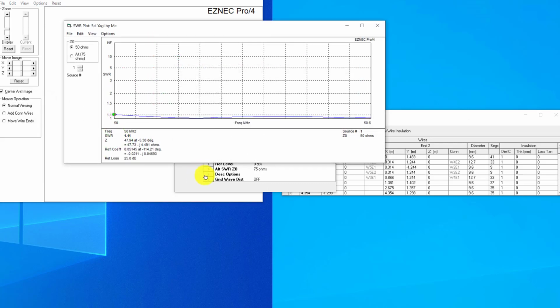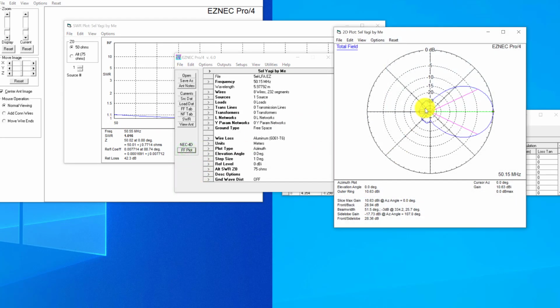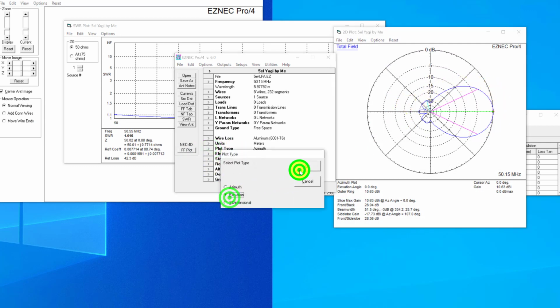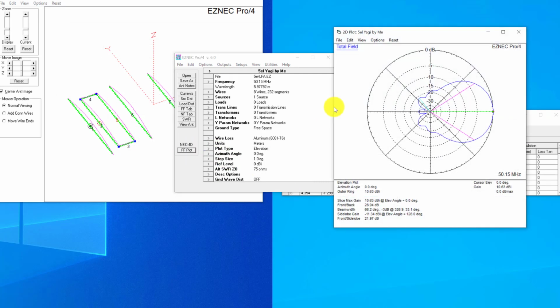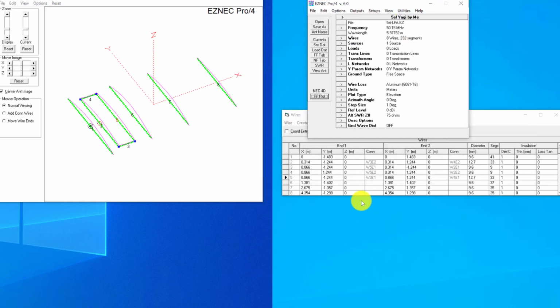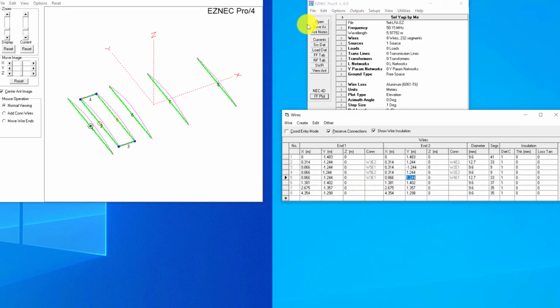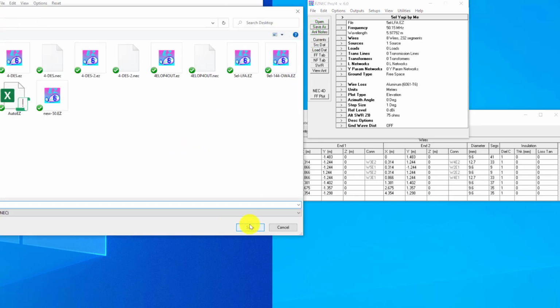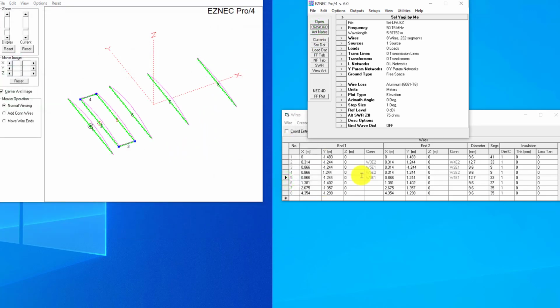we can now see that it's got a double dip, nice and low around 50.2, nice and low around 50.55, pretty flat in between, and then the azimuth plot looking from above the antenna, really nice and tight. And if I do the elevation plot again and have a look, that's pretty suppressed here as well, so it'll be good in a noisy location, this one. So all in all, that looks pretty good. That's the first Yagi built in software. So we're going to save that now, and we're all good and ready to go.